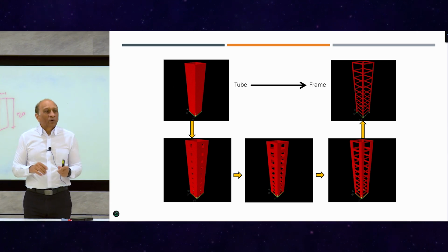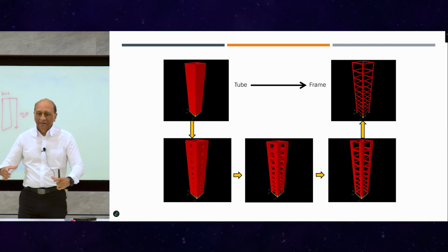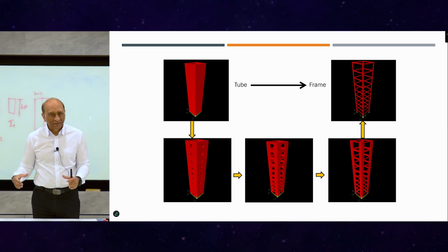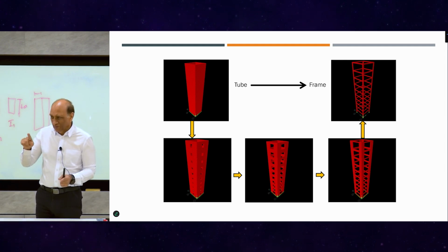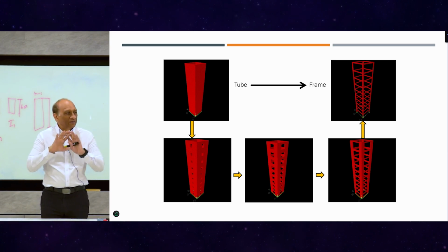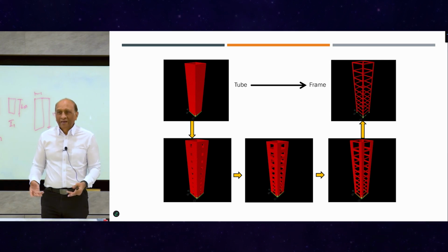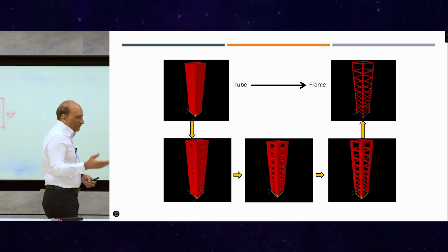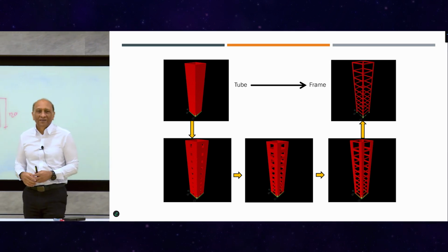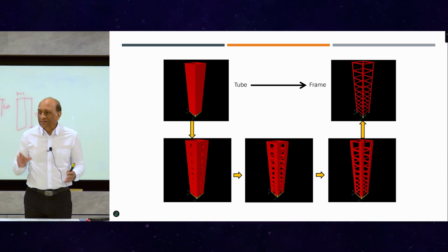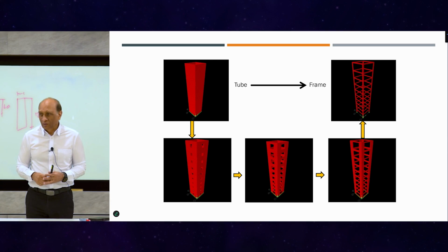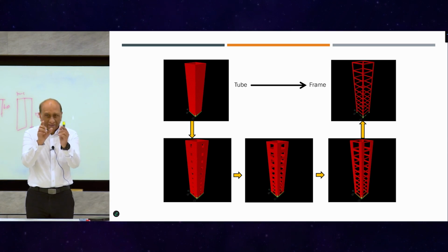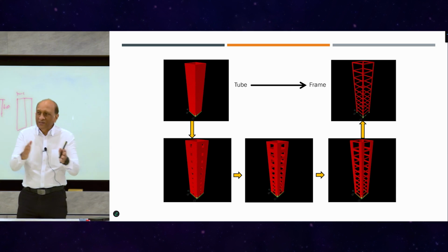Okay. And that was the idea, that we consider the building to be made of a solid tube first, then we puncture holes in it for the windows. So we go the other way. We don't start with the windows and put in the columns. We start with a solid wall and then talk to the architect: how many windows do you need? Right? Because at that time, SOM, the main company, really wanted to make a very tall building. So they said, okay, we will compromise on the window size as long as you can make this building, right? Because it was very tall.